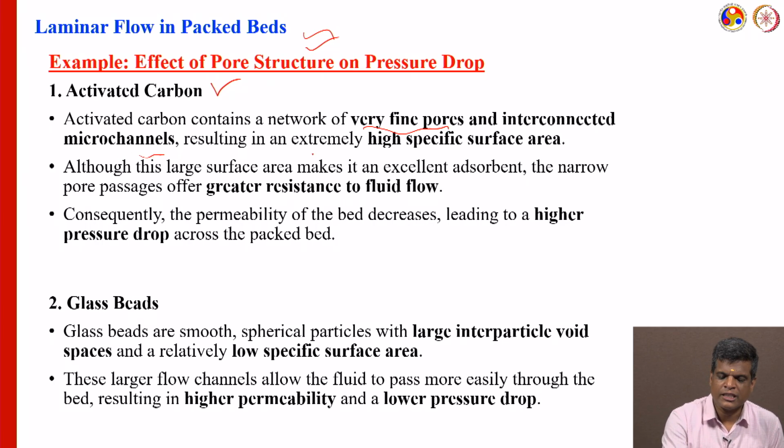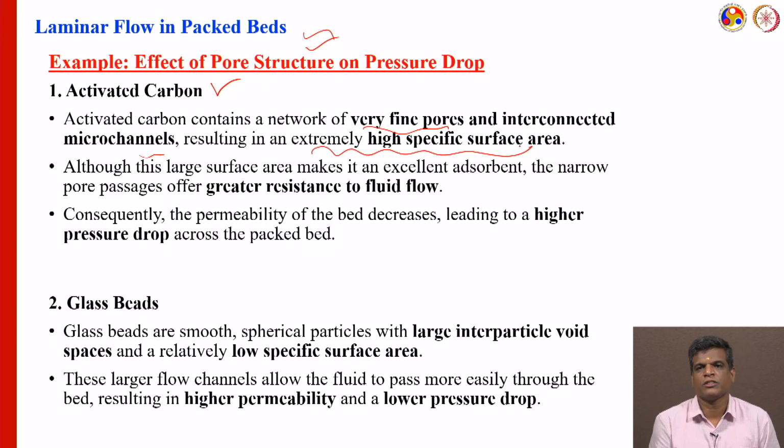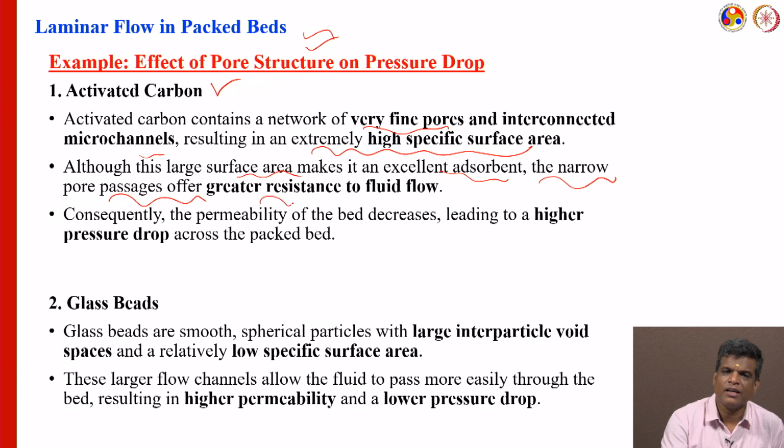It results in extremely high specific surface area, and is excellent as an adsorbent or biosorbent. The narrow pore passages offer greater resistance to fluid flow, so consequently the permeability of the bed decreases, leading to a higher pressure drop across the bed.